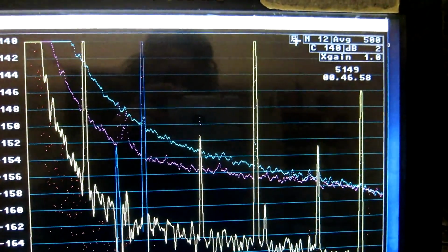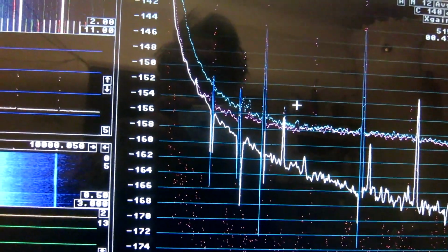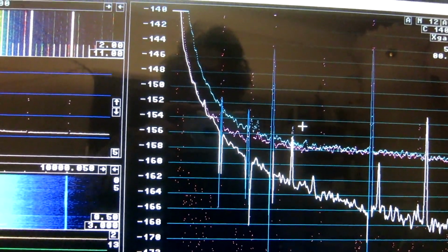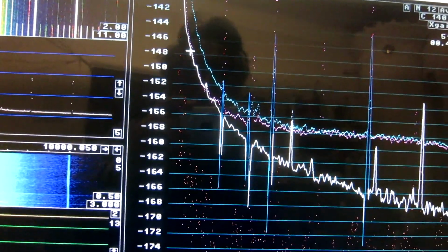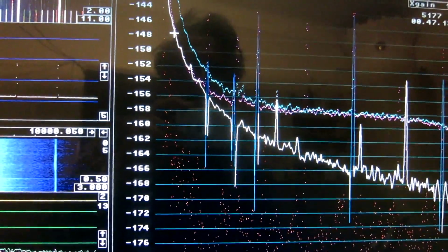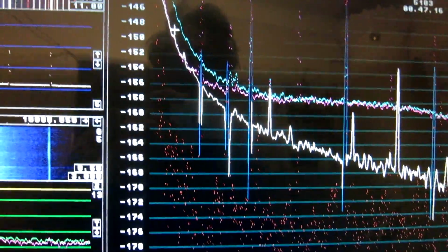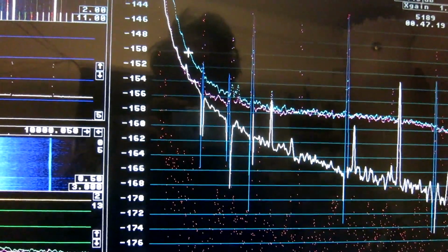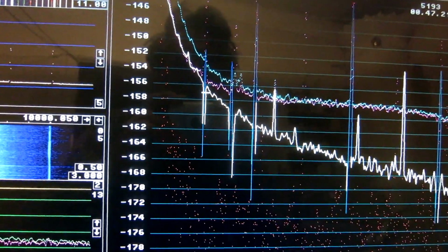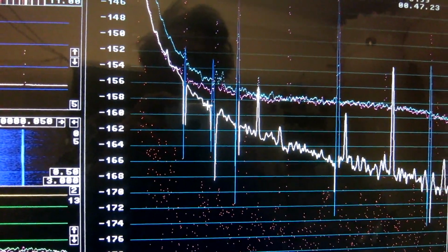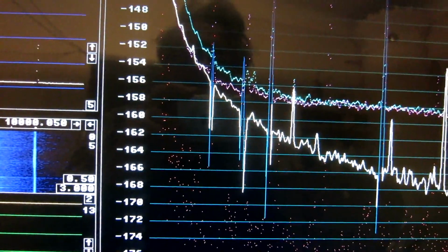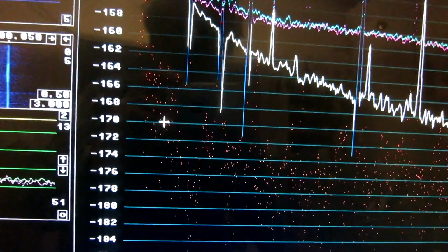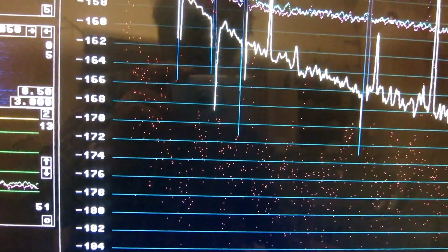I click once more here to come to the amplitude noise. And it's the same. Channel 1 has a lower amplitude noise than channel 2. But the amplitude noise is not so high, while the amplitude noise of the signal source is fairly strong. So here I have a very good evaluation of where the noise level is. The imaginary part is all the way down here.